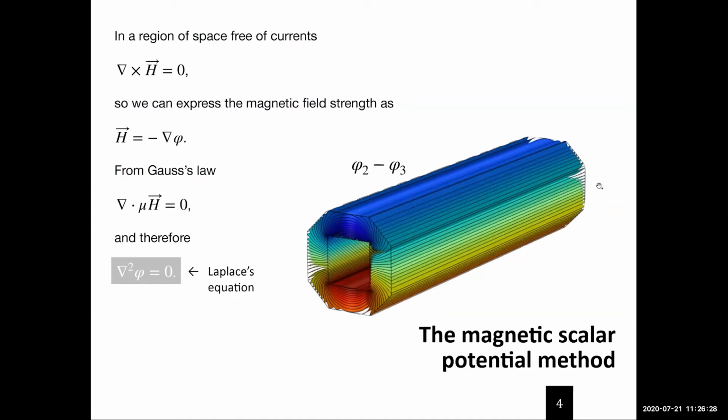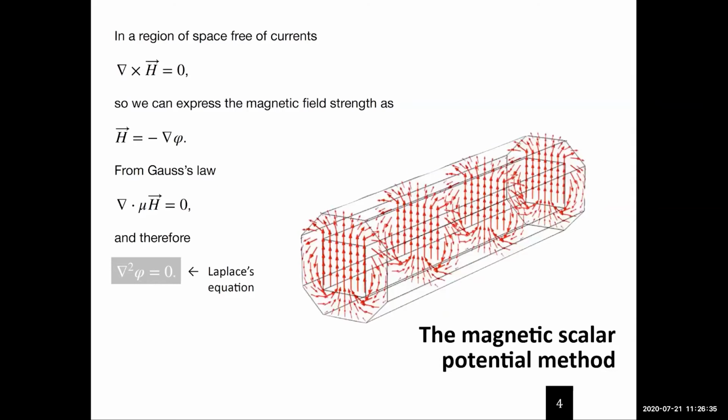So these black paths are the winding patterns that we need to use to produce the desired magnetic field, which is uniform in the inner square cross-section region, with the return flux forced inside this octagonal-shaped outer region. To solve for this and find the winding patterns, we use COMSOL Multiphysics.